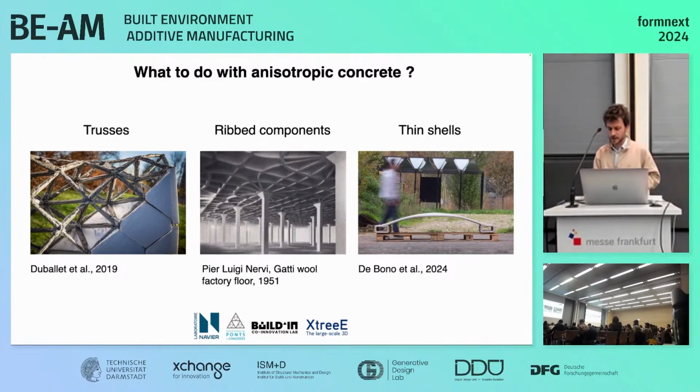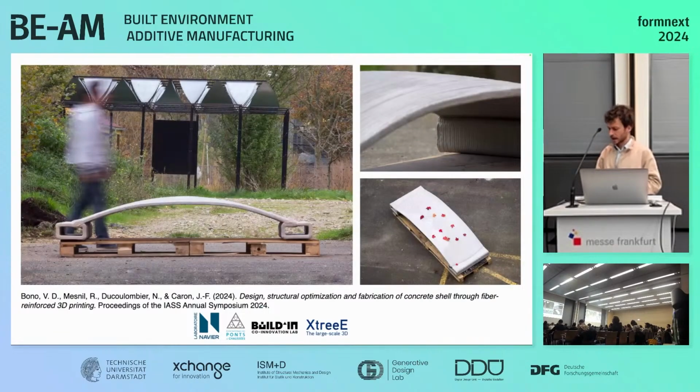And at the very right, we have thin shells. And this is not an arch, it's a shell. And you see that you have some little double curvature, as you see from the profiles. And this is reinforced with the fibers. And that's fine because this shell allows not only to retain distributed stresses, but thanks to the tensile reinforcement, it can also deal with localized loads. And the fibers are aligned in the main direction of this shell, okay?